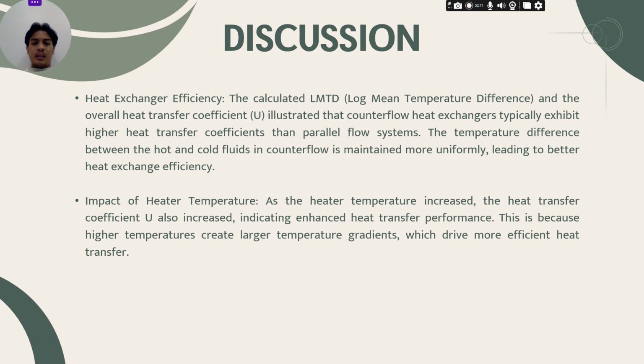The fourth one is impact of heater temperature. As the heater temperature increased, the heat transfer coefficient U also increased, indicating enhanced heat transfer performance. This is because higher temperatures create larger temperature gradients, which drive more efficient heat transfer.